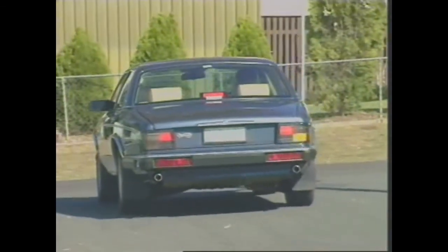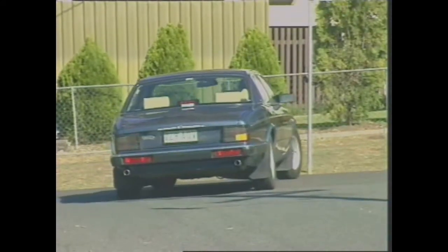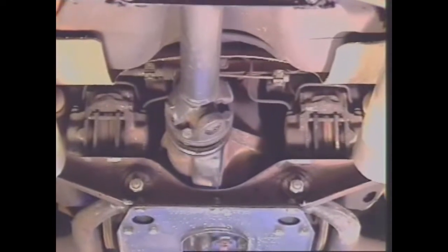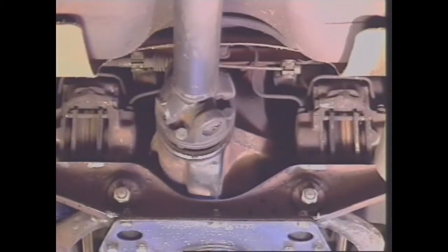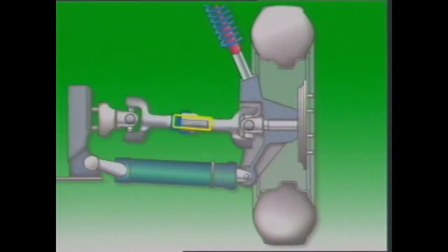On rear-wheel drive vehicles, the suspension arrangement has to allow for the external drive shafts to transfer the drive to the wheels. The final drive assembly is normally fixed to a crossmember, and since it must absorb the torque reaction, it must be secure. Drive shafts, either with conventional or constant velocity joints, transmit the drive to the wheels. When conventional universal joints are used, each drive shaft may have a splined section to accommodate changes in shaft length due to changes in wheel camber with suspension action.